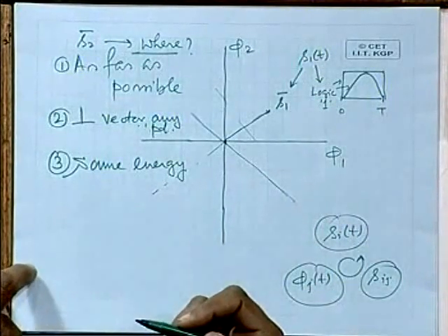If we have only two signals, then we can have only one basis function. We don't need two basis functions. That's another point, but I was going to extend this after one intermediate point. In fact, even when we have this example, what is that modulation scheme? BPSK is an example where you transmit two signals, S1 t and S2 t. You should think about the corresponding baseband signal set: +1, -1 perhaps. One is the inverted version of the other, where the scalar coefficient is -1. So you need one basis function, phi 1, to define the modulation scheme.